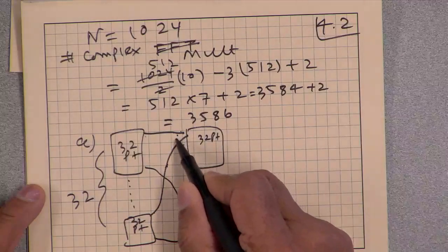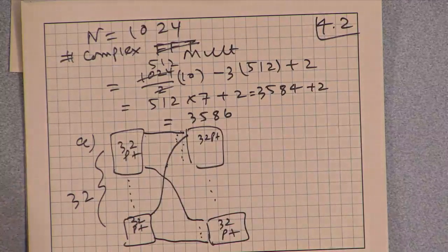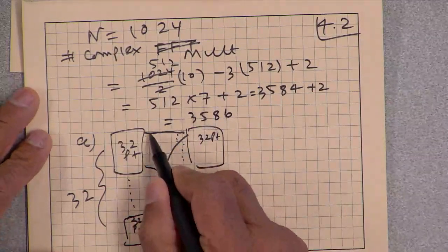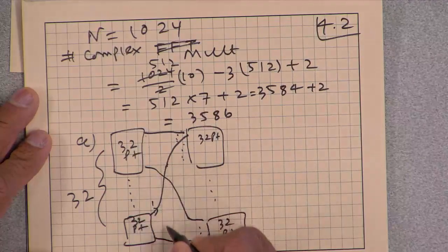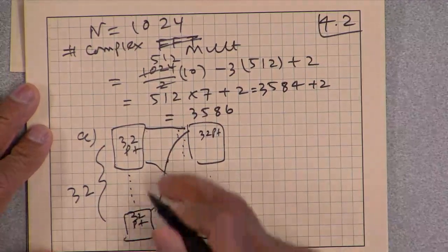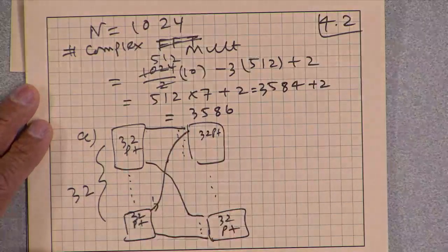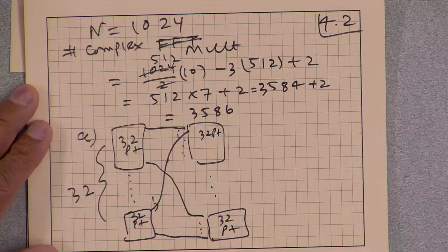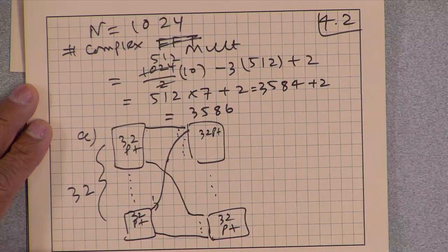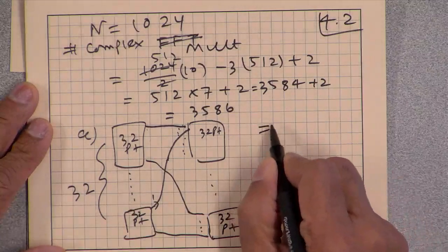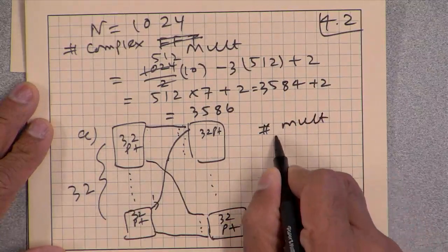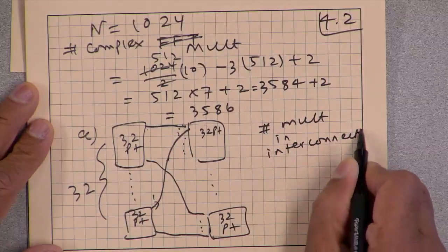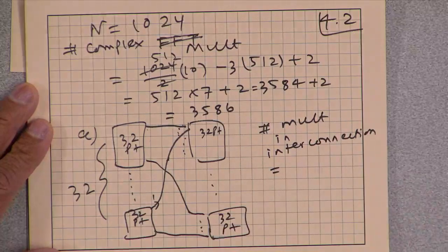Okay, so basically, what will be the number of twiddles here? So this is all 1, and this is 1. Any guess, any volunteers about how many twiddles in this composite FFT? (31 squared).